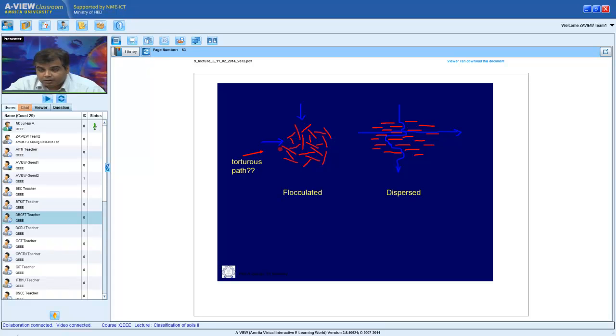So the flow, or the permeability, if I allow water to flow from one end to the other, as we will see later, is the nature of soil, how it allows the water to flow. We'll look at it later. For the time being, just visualize that the water has to flow. And what we say is the flow of water is tortuous for both directions. In other words, the flow would be similar, or can I just put a common word, the soil behavior is isotropic. Iso is same, tropic, so it has the same or similar behavior in both directions.